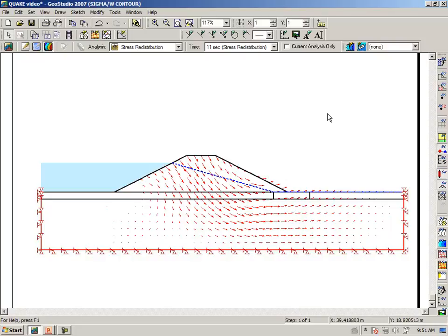You can do that on your own, but from a practical point of view, if I lower the undrained steady-state strength, then the factor of safety would also fall even lower, and since it is already less than 1, there is not much value in doing that type of parametric study. However, it would show you the changes in the permanent displacements if you were to alter the undrained steady-state strength.